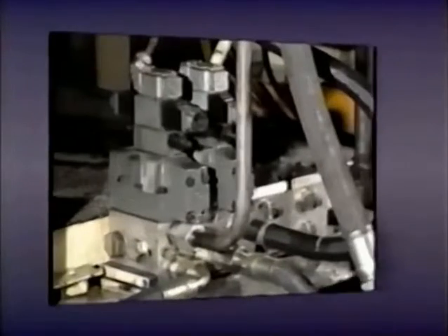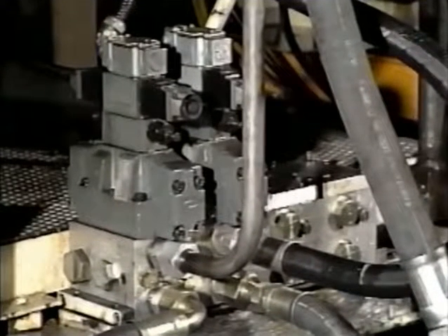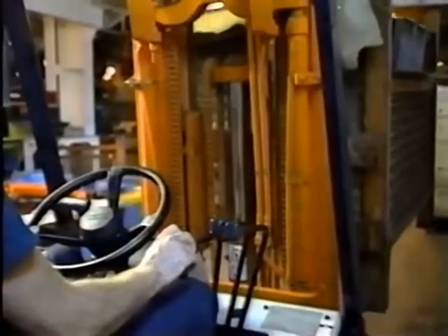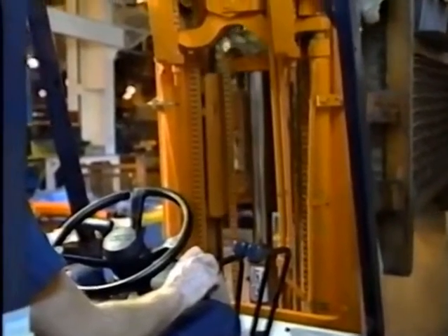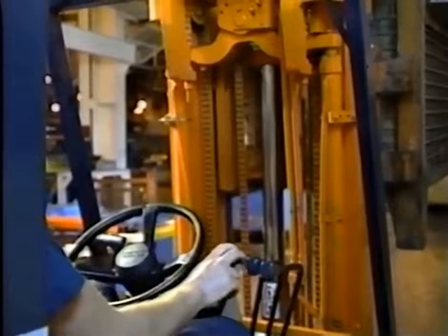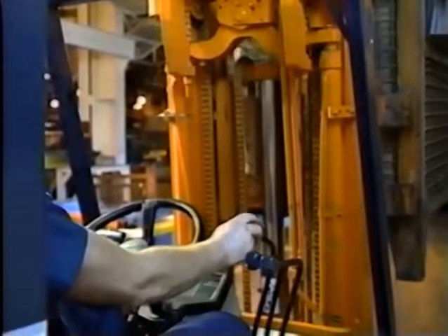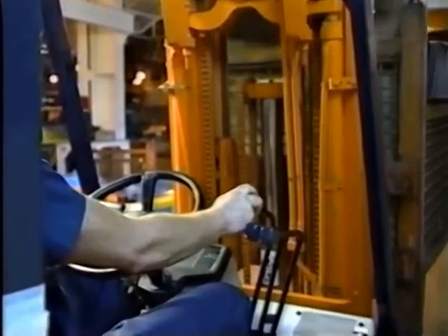The second kind of control valve we need to talk about is the directional control valve. These valves control the direction in which actuators move by controlling the direction in which fluid moves through a system. For example, a directional control valve on a forklift allows us to use hydraulic pressure and flow to raise the load or to lower it, depending on which way a valve control lever is moved. Let's see how this is done.